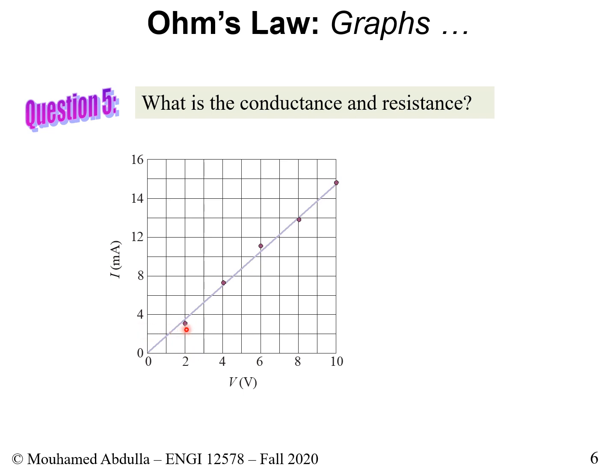So we got this current here, we put a dot. At 4 volts we got this current, we put a dot. At 6 volts we got this current, we put a dot. At 8 volts we got this current, we put a dot, and so on. Then we use regression or curve fitting, or not even all that. We simply place the straight line between the dots, and this straight line tells us the relationship between current and voltage. The dots are obtained experimentally, and the line is what we do after the experimental result that we got.